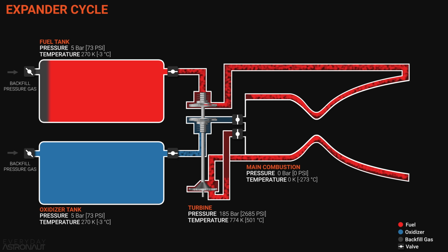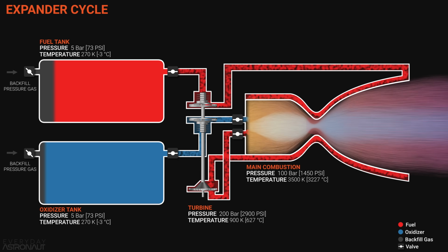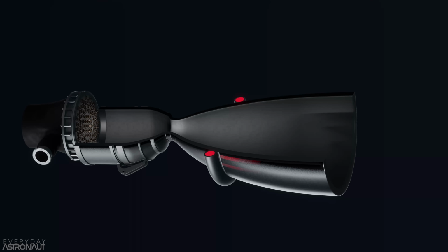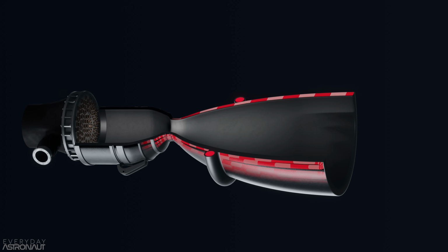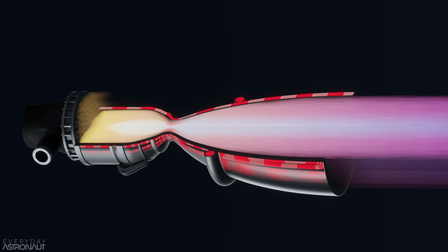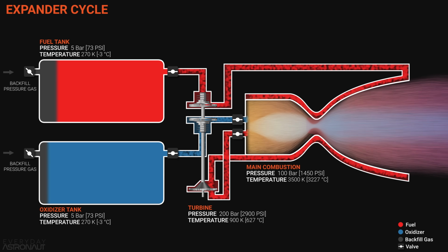Again, for those of you who watched my Why Don't Rocket Engines Melt video know, a very common and extremely effective way to cool a rocket engine is to actually pump the fuel through the walls of the combustion chamber and nozzle to help keep them cool. In the process of cooling the walls, the heat from the combustion chamber will be transferred into the fuel, where it will absorb some of that heat energy.